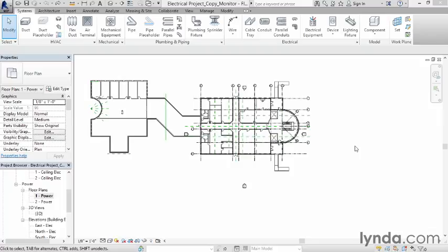Although we can see the levels in the architectural model, we need to physically have these levels brought into our own model. We can copy these levels, luckily, into our model, then establish a monitoring system even, to make sure that when an architect moves their level, we're going to get a warning that our model needs to be coordinated and reviewed. The objective of this video is to create the necessary levels by copying in the architectural levels and monitoring them for movement. To get started, let's go down to our OnePower floor plan.